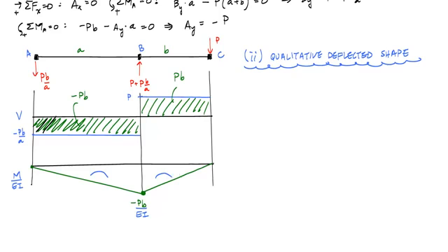And so let me draw my beam. And you have a sense from the concentrated load at point C that point C should actually move down. But let's take that out of the equation right now. Put it out of your mind, right? We just know that going from point A to point B to point C, the whole beam should be concave down. So with no boundary conditions, you would probably just say, oh, it probably looks something like this. But the reality is that the boundary conditions at point A are a pin, and at point B a roller, which means that I should have no vertical displacement at point A and point B.